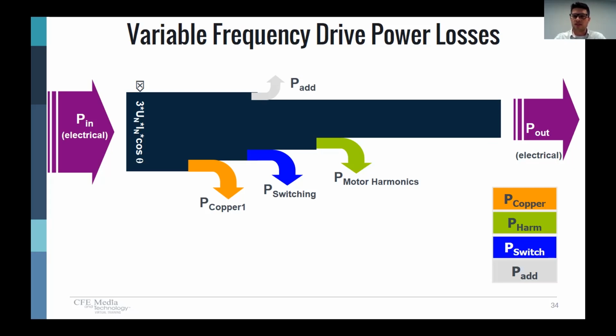Of course, there are power losses inside the VFD. They get hot when they run, so you know that some of that energy is being transferred into heat and not being used 100% efficiently. But you do stand to make some other gains when you add a VFD. So we'll talk about those different things and how you can save energy in your system by introducing a VFD into it. A VFD has some losses, as almost any electrical component will.